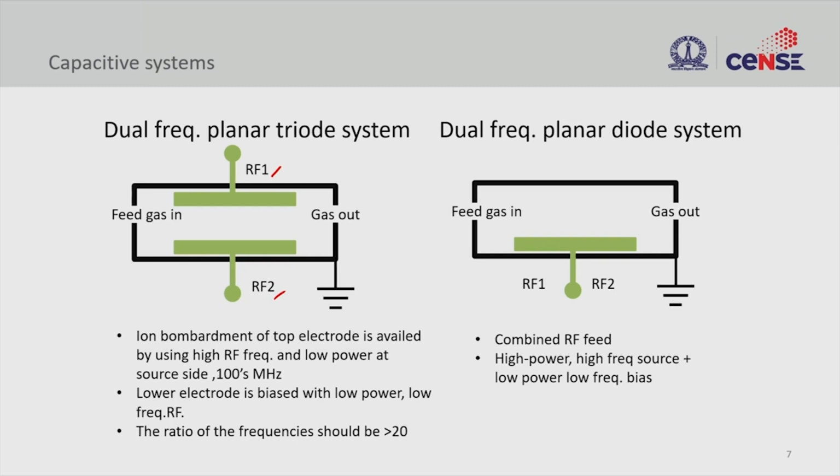And the lower electrode is kept at a lower frequency, and this is where you keep the wafer and so on, and then you can use your gases that are fed through the system to generate the plasma with this dual frequency configuration and do the etching. So what we avoided by using dual frequency is etching of one of the electrodes, or the sputtering of one of the electrodes itself. So this is how this was handled.